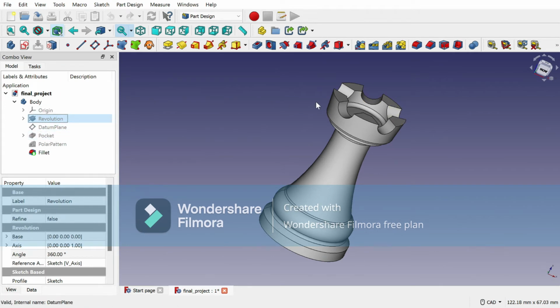Now once the groove was created, because I selected the option pass through all, then I selected the polar pattern option and rotated it about the z-axis in order to make such a groove on all the sides of my model. Then I selected the fillet option.